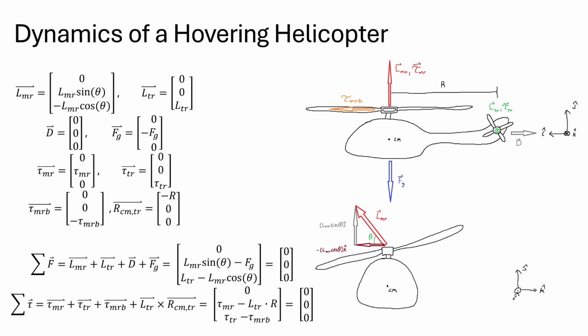And then we have the torque generated by the tail rotor that we also needed to account for. And we can see that that is accounted for by the torque generated by the swash plate. And so that torque will cancel out the torque from the tail rotor, and so everything will balance out to 0. And of course, a lot of this will depend on the actual aircraft specifications and the specific rotations per minute of each rotor, but we can control all of that, so we know that this equation can balance out to 0, and this shows exactly how a helicopter is able to hover while having 0 velocity.